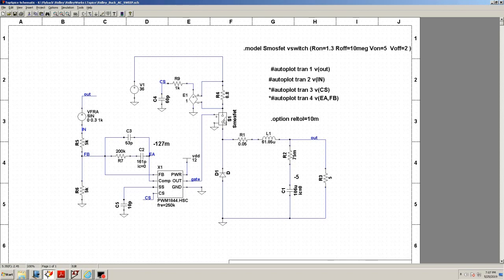This is a switch which is emulating a MOSFET, and then this is your buck, and the output gets connected back into here. So basically it sends a signal out, and then the signal returns, and the FRA measures the amplitude difference between the out node and the in node and plots the gain and the phase. Okay, which is a very powerful tool.